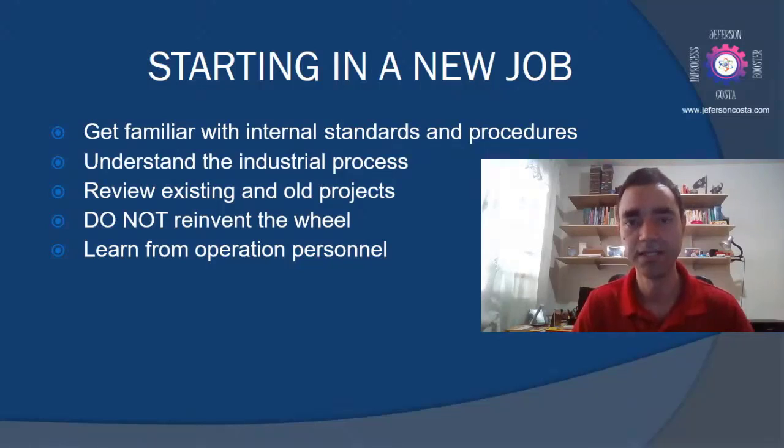Sometimes we do a site survey, which means that for an existing plant, our company is hired or contracted to do revamping or add new components to the plant, and a small group goes to the field in order to evaluate what's happening, whether the pipe instrumentation diagram is really updated, and so on. That is the moment you need to use to talk to the operation personnel and try to clarify as many questions as you have.